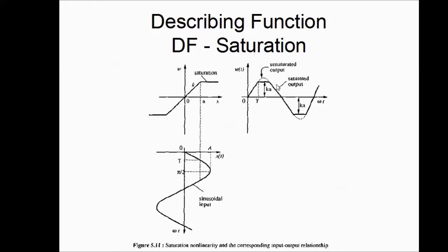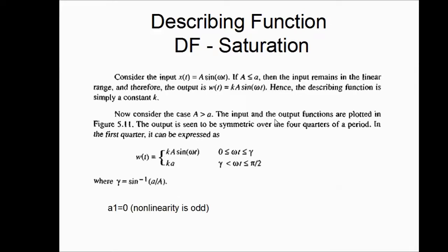So this is the saturated output here. This is the unsaturated output, the dots. So that is the actual sinusoid. The saturated output is shown in the dark line here in the output graph. So we use the output graph and its values. Its piecewise definition is used for constructing the describing function. So this is our piecewise definition, obtained by using the graphical procedure we just showed.